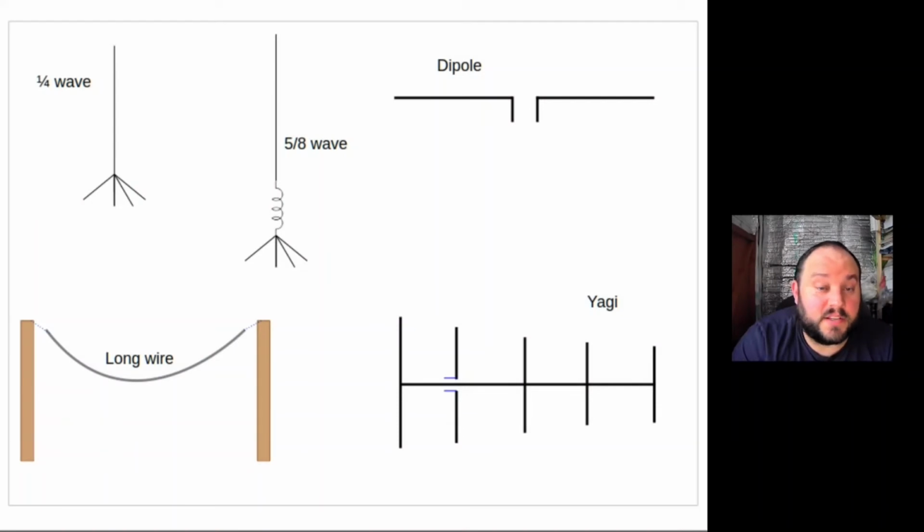There are many antenna designs, and these tend to be the most common. You may have seen these types from your day-to-day travels. The first aerial here is the quarter wave vertical aerial on the top left. This is popular in the hobby because it works great for UHF and VHF frequencies. A quarter wave on these bands tends to be compact enough to attach to a vehicle or house without being too offensive to the neighbours and without being too tall, hitting trees or bridges.